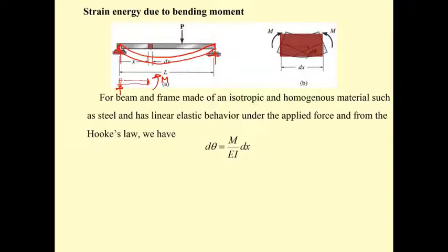And if you go back to the elastic beam theory, what do you have? Under this, you have the deflection here, phi, and then you have the slope. The slope here is going to be theta. The theta is going to be d phi by dx. And then you may measure the radius of curvature.